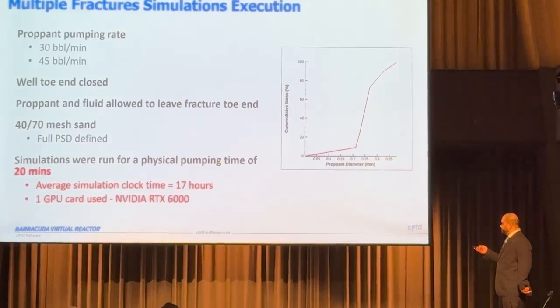So again, the GPU acceleration of Barracuda is where the strength is. Some of our users who have used traditional CFD tools came to us with this problem because while their traditional CFD tool was solving the problem, it was taking them about 5 weeks to get it out, even with 2 fluid models. And DPM was almost impossible to solve at this scale. So this is where, again, the strength of MPPIC technology lies.